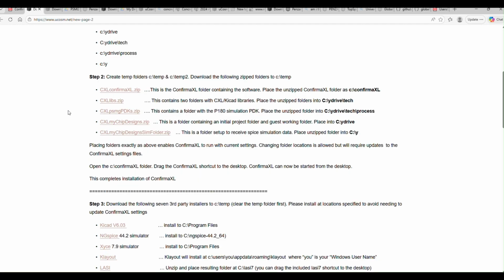So we're distributing this with the initial PDK. It's from the Predictive Semiconductor Modeling Group. This is a predictive PDK that emulates a 180 nanometer semiconductor process. So if you're using TSMC or TI or another 180 nanometer process, but maybe you don't have access to the PDK because of NDAs, we certainly can't distribute those kinds of PDKs because of the NDA problem.